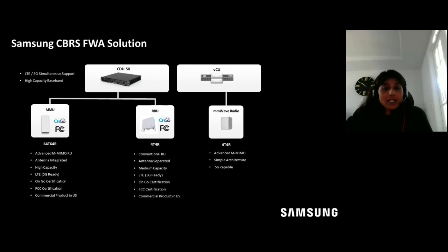It's a conventional RU system and supports both internal antenna and an external antenna. The CBRS 44R product works across 150 megahertz of spectrum and supports the complete band for CBRS. As I said, another very interesting band for these deployments, which can be considered as millimeter wave, and especially for the operators who hold the spectrum in this space, right?